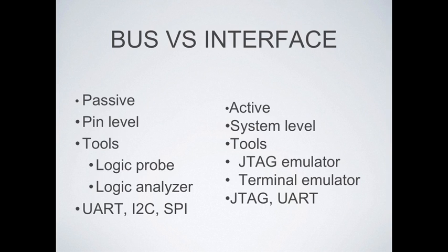And then there's a logic analyzer, which is useful when you have an address of data or a lot of data coming over more than one pin. Then that's when you want to use the logic analyzer. And the types of protocols that you would see over a bus interface essentially would be UART, I2C or SPI. When I'm talking about interface analysis, that goes a little bit more active in some sense.